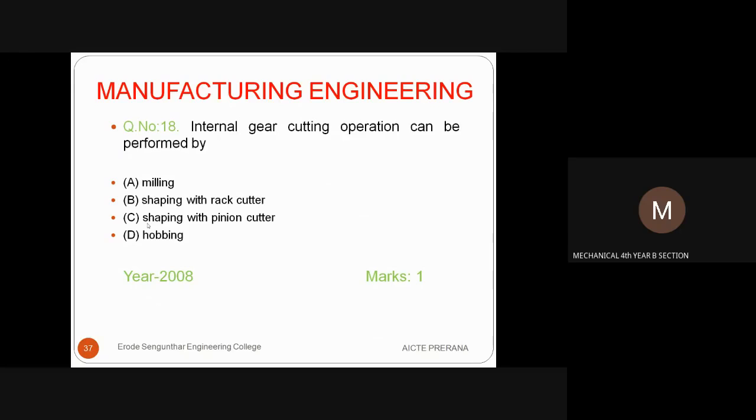So option C is shaping with pinion cutter. Here the answer is the pinion cutter, because you are well aware that with the help of a pinion cutter only it is possible to cut the gear profile on the internal diameter.